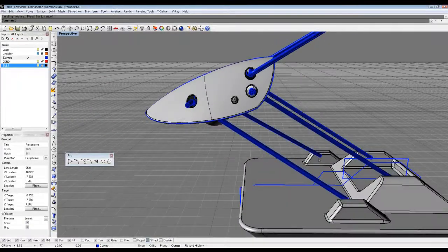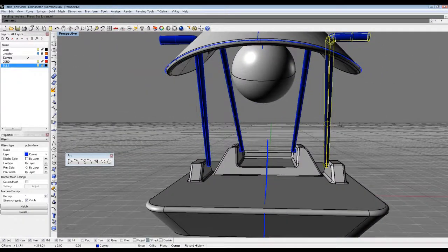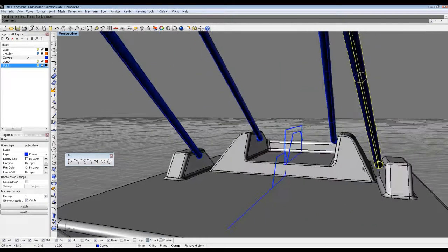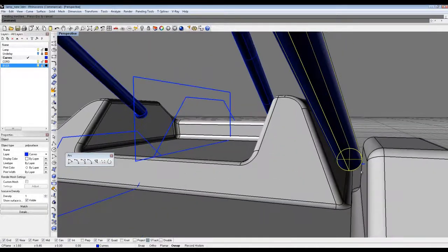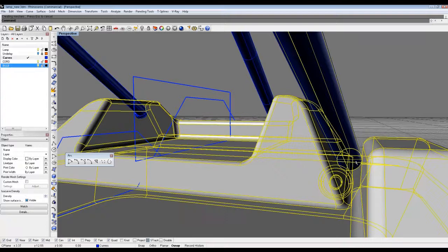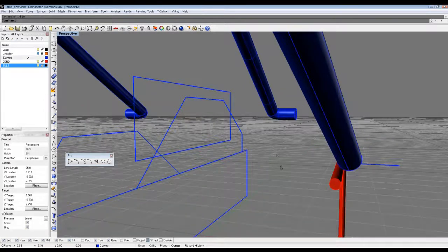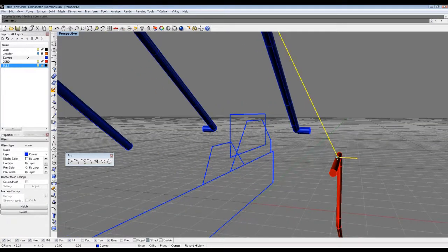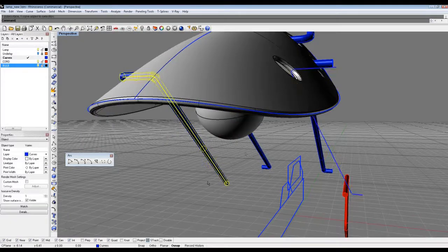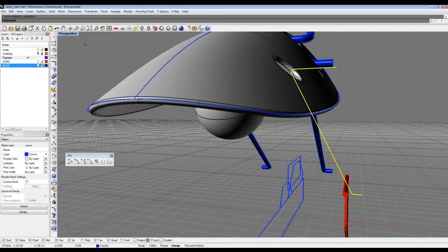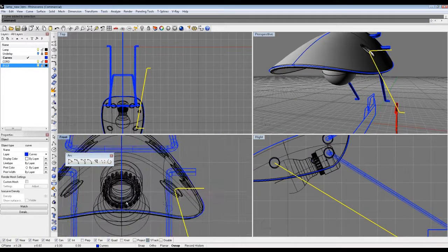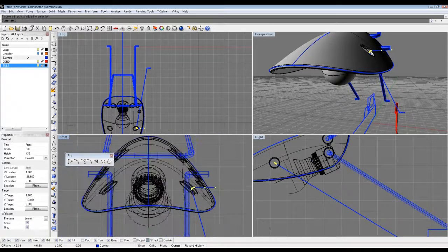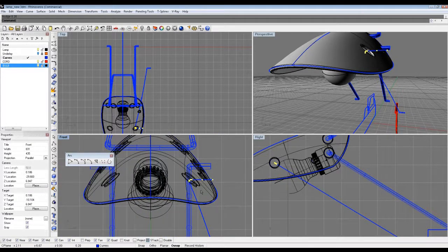The other thing I'm noticing here is having a little bit of an issue with where the curve that created this pipe didn't actually pipe all the way, and that's probably because these didn't join. So I will go ahead and remove that and just make sure it's all joined up. And while I've got it here, I think I'll actually move it in slightly by turning on its points and just shift it over. Now I'm just hitting Alt right arrow, and that's nudging it into position.